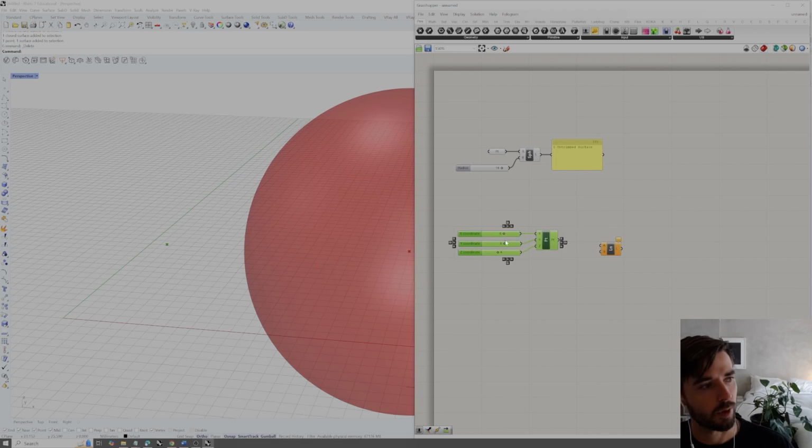Well, we already have one point here that we've constructed inside of Grasshopper. If we want to make another, we can select all of these components, left click, hit Alt, and drag down, and we now have 2 points that are both the exact same value. So 6, 6, 4, and then we have one at 6, 6, 4. If we plug each one of these, one into the start point A and one into the end point B, then we'll construct a line that has exactly no length.